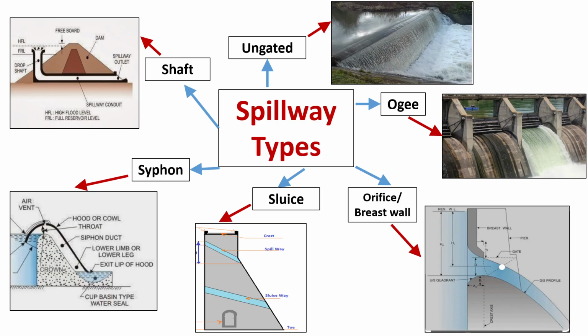We all know that discharge is proportional to head. In this spillway, head is increased by lowering the spillway. This is used for passing high discharges, and sediment also can be released through this spillway as these are placed much below. The other types of spillways as per the project needs are sluice spillways, siphon spillways and shaft spillways. For earthen dams, side channel or chute spillways are also used. A separate video on spillway types is already available on this channel.